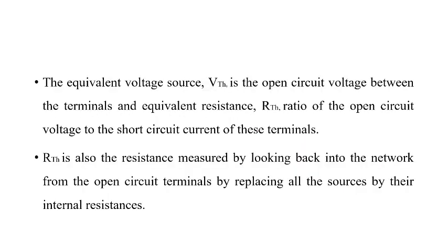And as far as VTH is concerned, VTH is your open circuit voltage between the terminals, and the equivalent resistance RTH is the ratio of open circuit voltage to the short circuit current of these terminals. And your RTH can also be measured by looking back into the network from the open circuit terminals by replacing all the sources with their internal resistances.